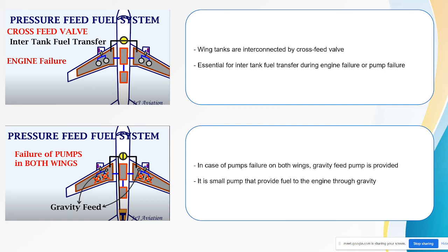Usually, when this sort of problem occurs, where fuel cannot be fed into the engine at optimum flow, the airplane will fly at a lower altitude to help increase the pressure inside the tank, so as to help more flow for gravity feed.